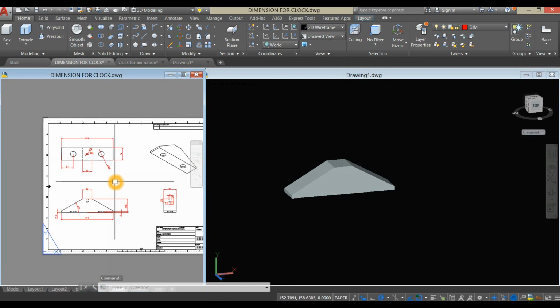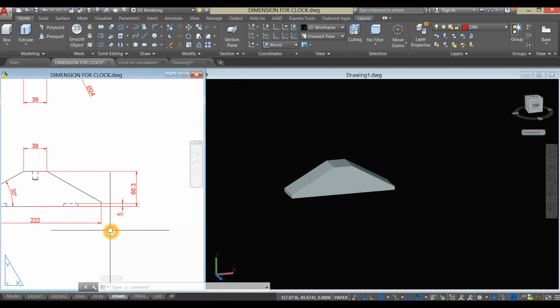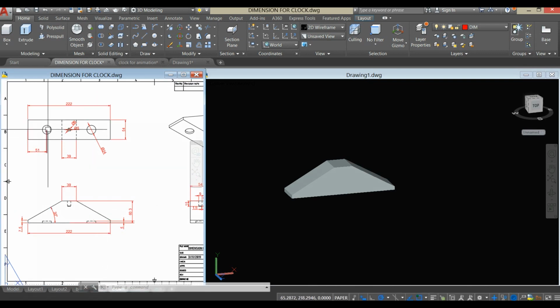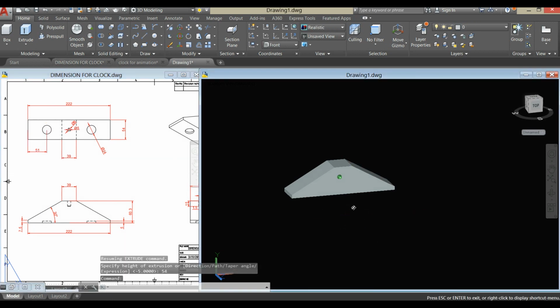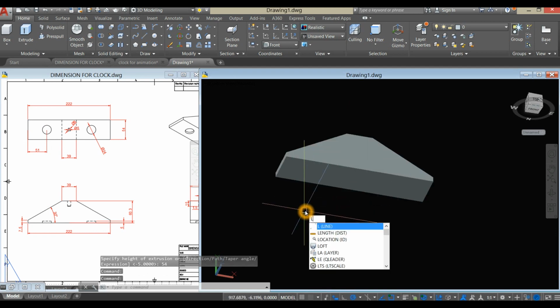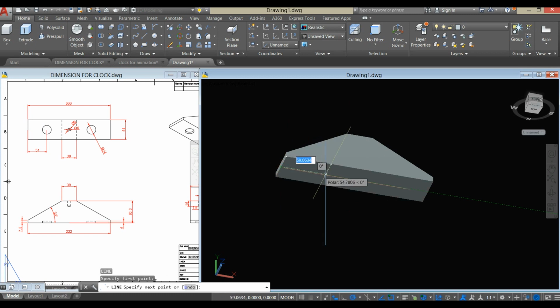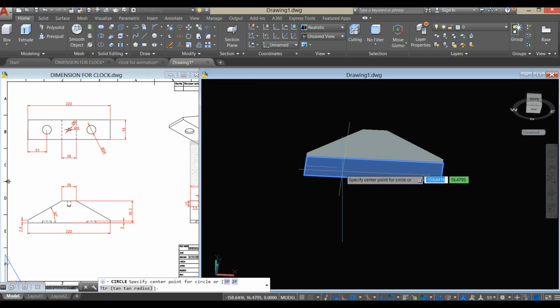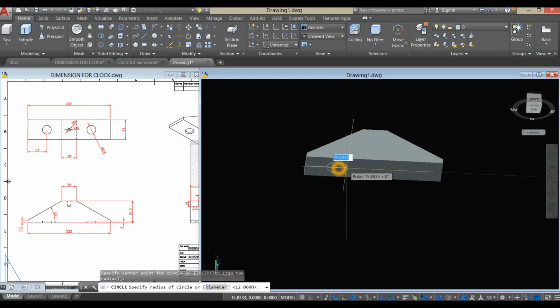Now I'm going to poke a hole from the bottom, and the thickness for that is 5, and the distance from this point to the center is 51. So again, I'm going to draw a construction line. So line, type L for line from the midpoint, bring it to the right for 51 units. So I'm gonna click circle and click the endpoint there and enter D for diameter option and enter 24.